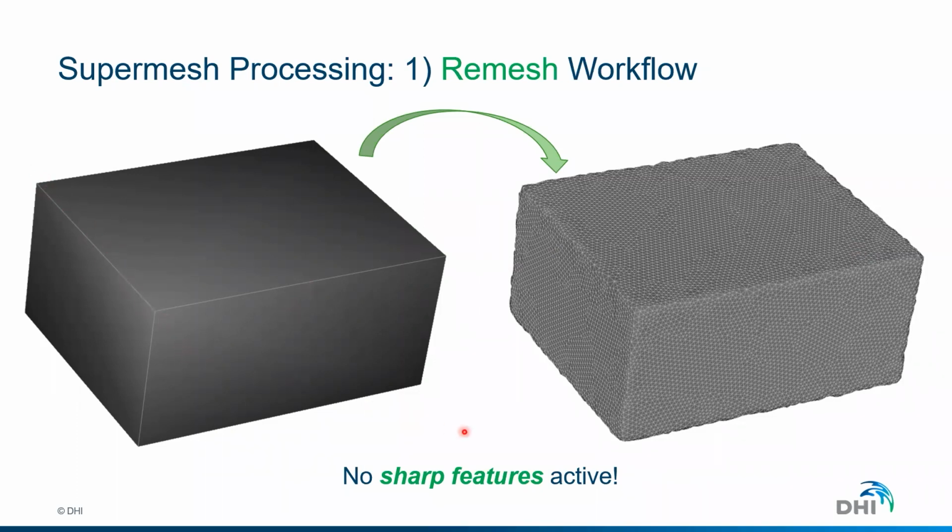If sharp features is disabled, we see the whole thing as a surface, so there is not enough information to tell there is a cube and that the 90 degree angle between the faces has to be preserved. This can also be very positive in cases where you do not really need to preserve the edges, so you can smooth your surfaces, and there are more chances to fix the problems, correct the triangulation issues and the intersection issues.